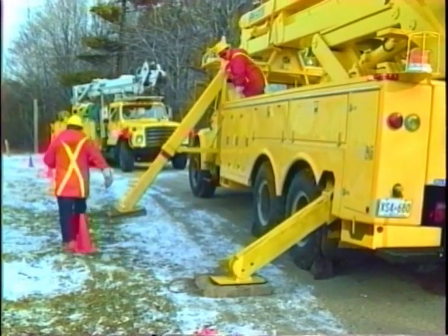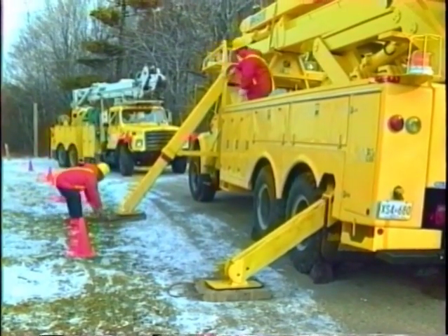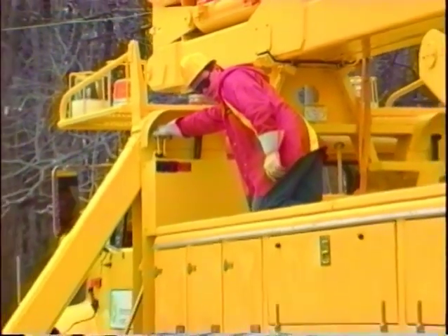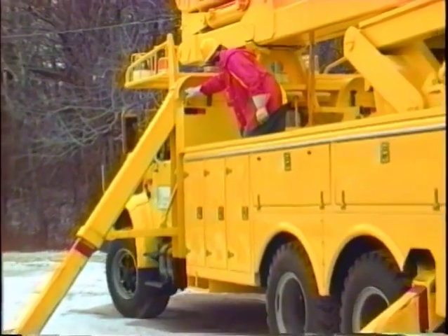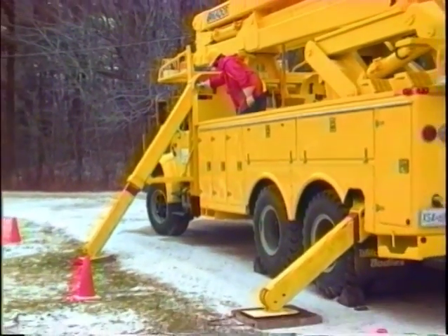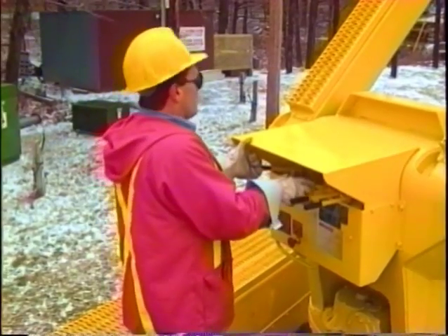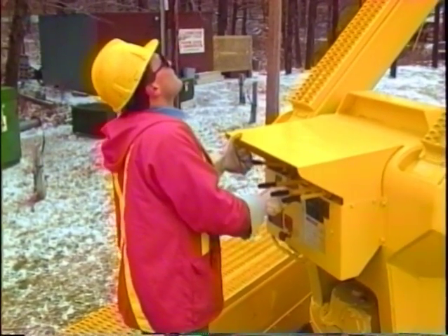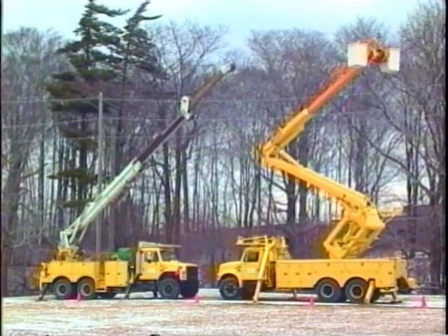Don't cut corners when setting up your unit. Make sure it is stable. Check the holding valves on your bucket truck or RBD daily. Work the controls smoothly. Listen to what the hydraulic system is telling you. The key word in dealing with your RBD or bucket truck is respect. Treat your unit properly, and it will return the favor.